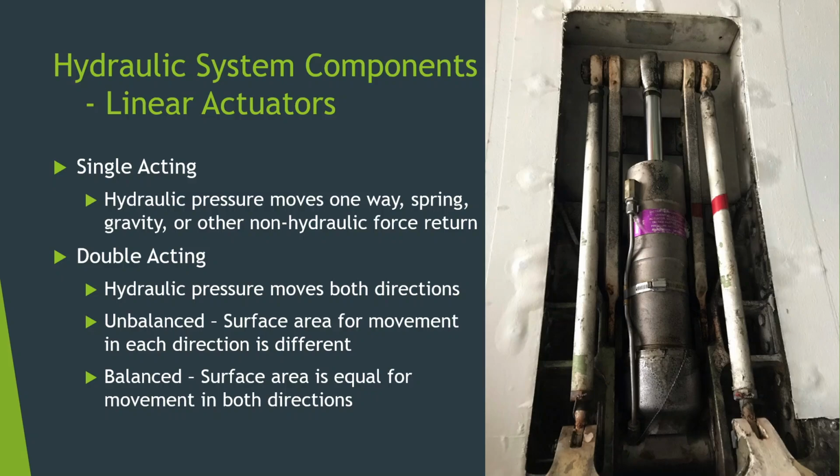Now, it did have a certain amount of hydraulic action that occurred to help lock it down, but most of the action required to push the stairs down was simply gravity causing it to free fall. And so in that instance, if hydraulics were off, you could still open the stairs. Or like a big cargo door, the ones that open up on the side of the plane, if hydraulics are off, most of them are able to close just by releasing hydraulic pressure. And so those are some other non-hydraulic forces you can use for the return.